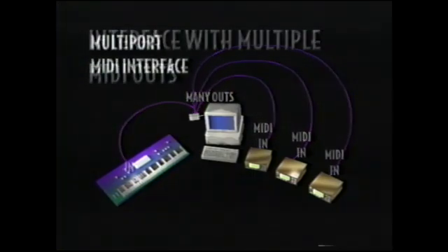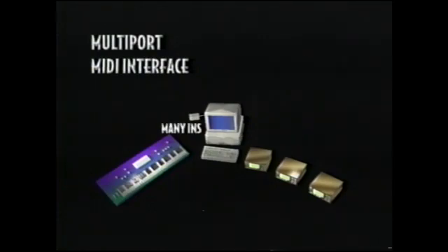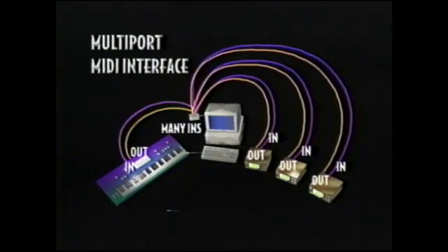If you have one of those deluxe multi-port MIDI interfaces like the Opcode Studio 4 or Studio 5, connect all the MIDI outs of all your MIDI devices into a MIDI in on your interface.